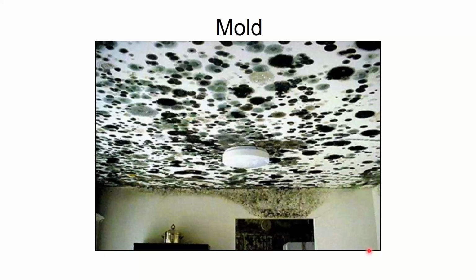If the moisture is coming from a roof leak, it's the roofer's problem, right? Or sometimes you might have it in one isolated area, and maybe there's a pipe behind that wall. Maybe there's a plumbing pipe or a hydronic pipe that has a leak. So you might have just that one 16-inch wall cavity with some mold issues, and then you go a couple cavities over and everything's fine. So you've got to rip that open and see if there's a pipe leak back there.